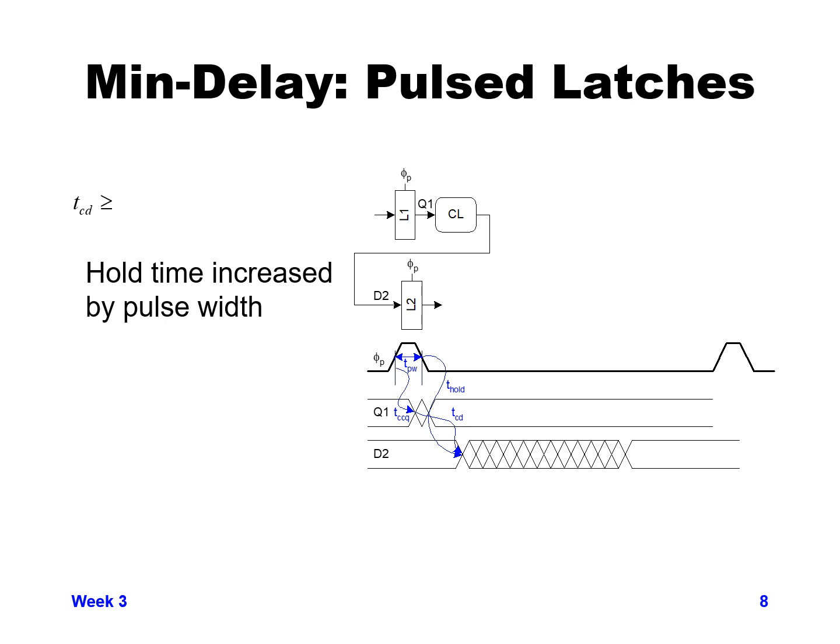And then it goes through the combinational logic to D2 and has a contamination delay time through the combinational logic to D2. And you can see the arc going to the earliest that D2 can change. Now, this is compared to the closing edge of latch 2.